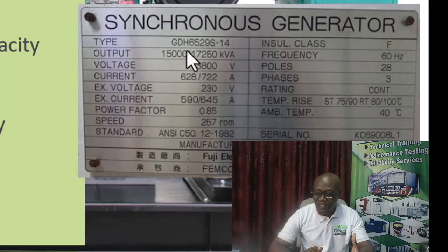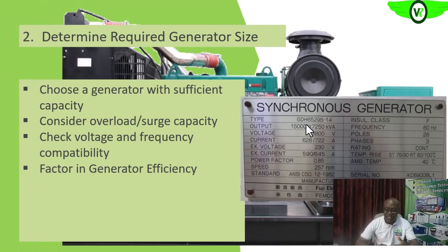If the efficiency is, you also see it in the data sheet, say 98%, it means that 98% of this power rating on the nameplate will be available for your use. And remember that of that 98%, it is 80% of it that we need to use. Remember.